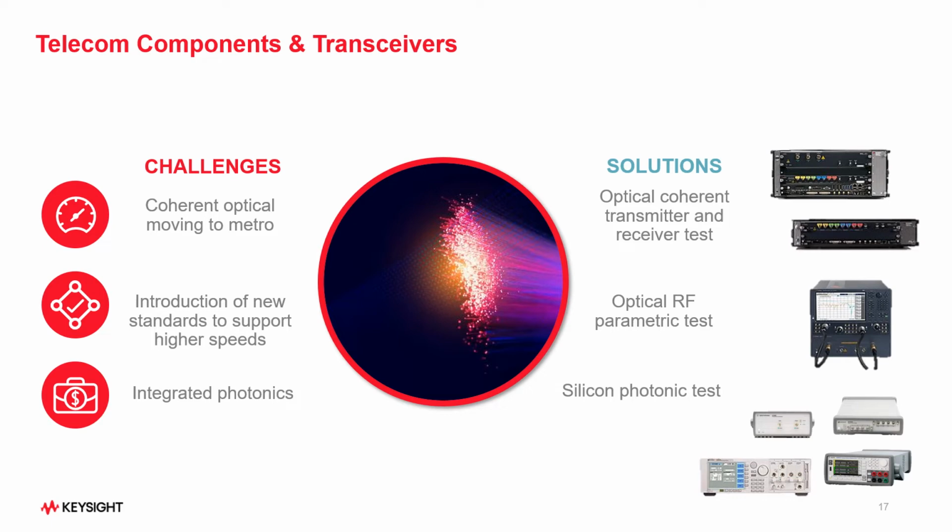The next piece, like I mentioned earlier, is to do very high speed gigabit device testing. Electro-optical and optoelectrical components used in coherent optical transmission systems have unique test challenges. For example, to test dual polarization IQ modulators and intradyne coherent receivers, it is necessary to measure the insertion loss during transmission. To fully characterize optical coherent devices, one needs to analyze many parameters, which include bandwidth, gain, imbalances, and then group delay and skew.